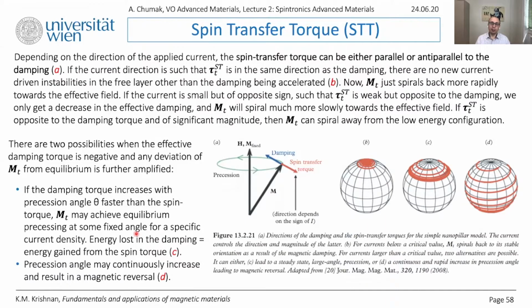The spin transfer torque nano-oscillator is one way to go, and another way to go is to use the spin Hall effect, as we know. When you put two magnetic layers and then on top you put platinum, then instead of sending current through your material, you can send current along the platinum. Then, as we know from the spin Hall effect, it will create spin polarized current that transfers to the surface, and you will induce spin polarized current into this layer. And this will be exactly your spin transfer torque.